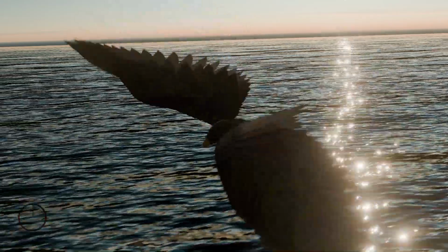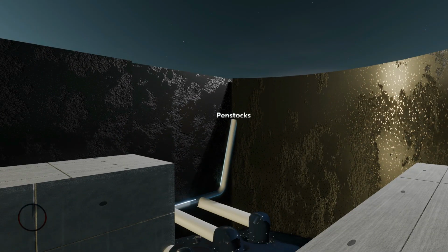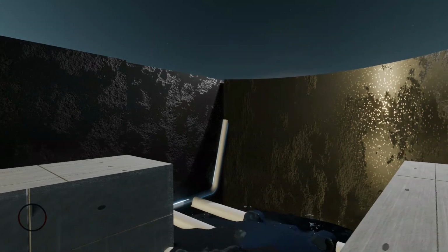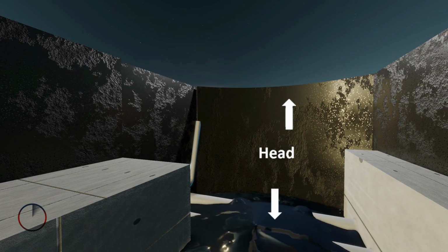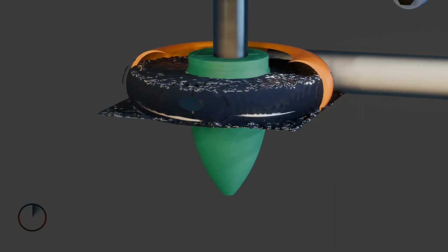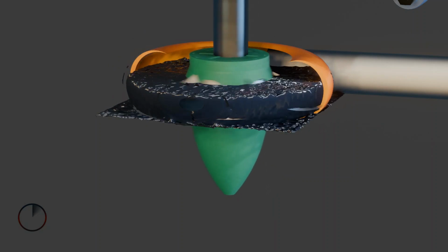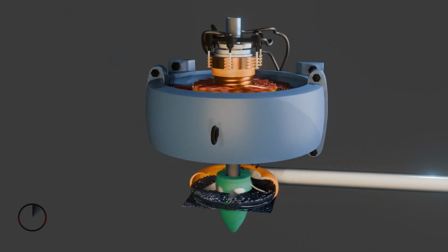In the generation of hydroelectric power, water is collected or stored at a higher elevation and led downward through large pipes or tunnels, usually called penstocks. This is then channeled to a lower elevation. The difference in these two elevations is known as the head. At the end of its passage down the pipes, the falling water causes turbines to rotate, and the turbines turn the shaft of the generators, which convert the turbine's mechanical energy into electricity.